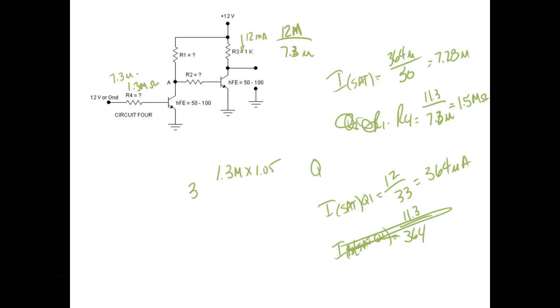So every transistor you go through, you get a current gain out of it if you design your circuit right. So we're getting over 1,000 gains. So whatever's driving this thing is only required to provide a tiny current. We could set up a touch pad on this, very easy, and just touch between ground and me, and it would saturate or turn a light on, because my body can provide 7.2 microamps, right? This is almost nothing. We could probably stick an antenna up in the air and pick up radio stations, but it's a saturated switch, so it wouldn't do us much good.